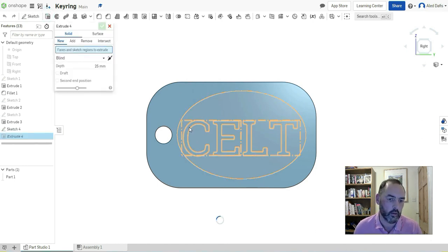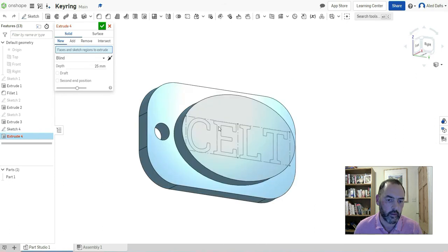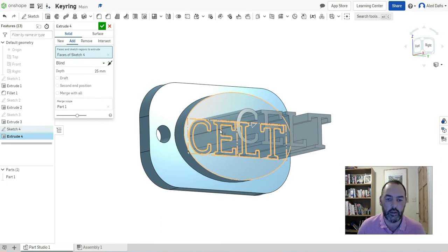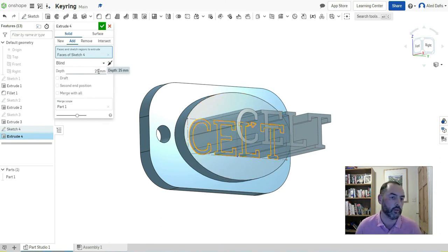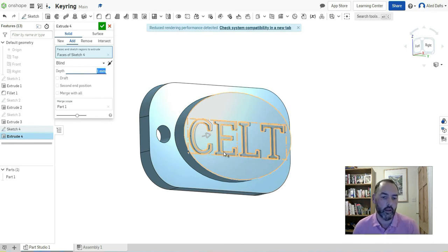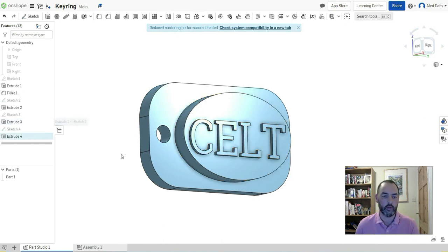I'm going to pick, let's zoom in now, then that's extruded that, so I picked extrude, picked the text, and it's extruded at 25mm, which is way too long. I'm going to make that 1mm. So we have raised lettering as well, like you'd have on the branding, maybe on a super dry jacket or something like that, with the flexible rubber branding. But we can do exactly the same here, and then we can take this and 3D print in our flexible materials. There we are. So we have raised lettering as well.